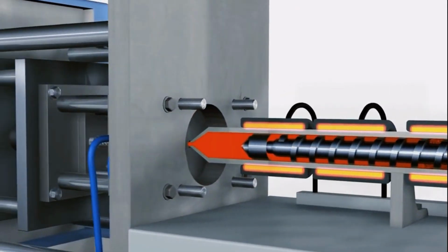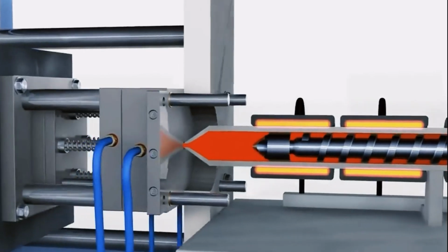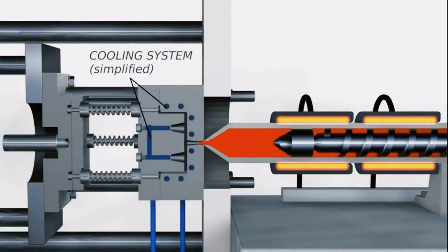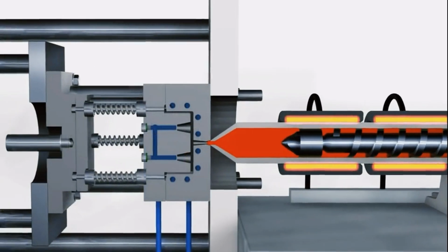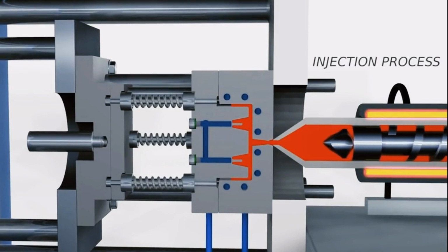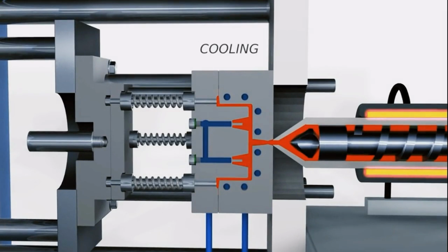During the injection process, the plastic melt fills the mold cavity at a certain pressure and speed. There are various filling methods, such as rapid filling and segmented filling. Rapid filling can make the plastic melt fill the cavity in a short time, but it may lead to air trapped in the cavity and produce defects. Segmented filling can control the filling process more reasonably and improve the molding quality according to the structure of the cavity and the flow characteristics of the plastic.